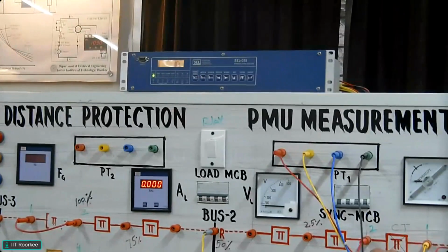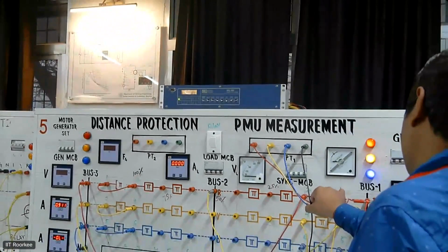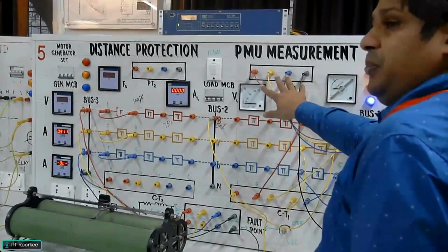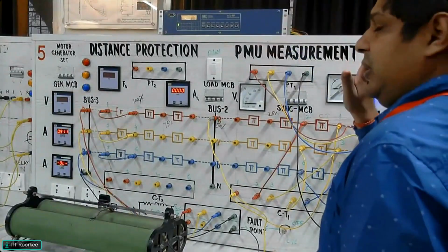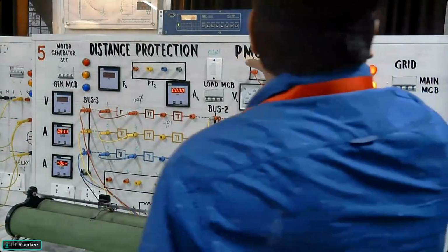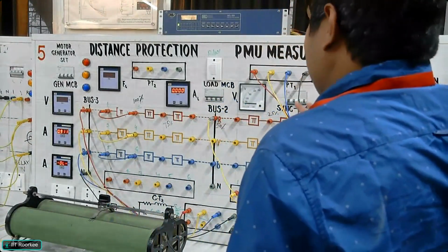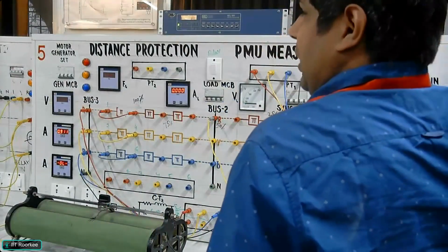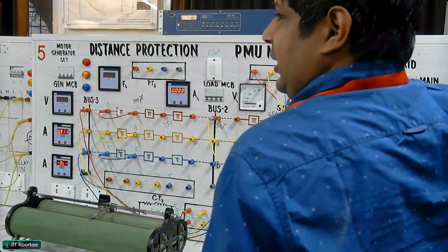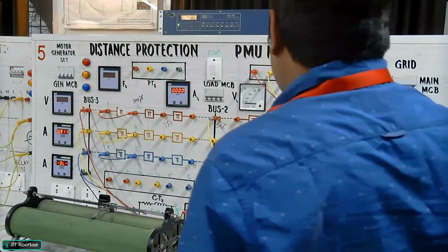Similarly, this bus data, this bus's 3-phase voltages, we have given to a PT, and the secondary of the PT we have given to the relay. And this relay is connected to this system through a LAN wire. So basically in this course, we are focusing on how the data is being transferred and how we are monitoring it. So the main focus will be there.